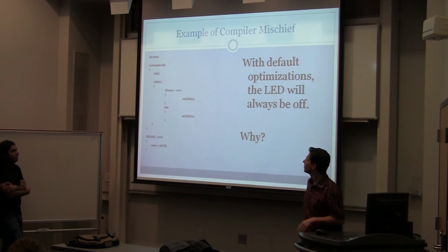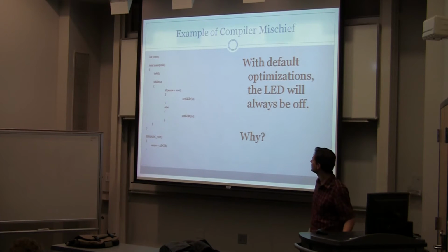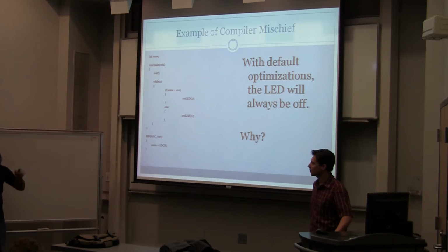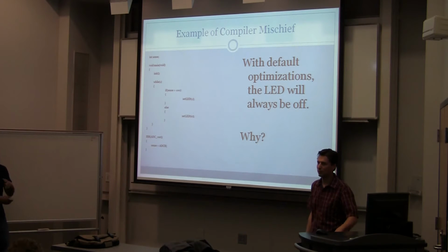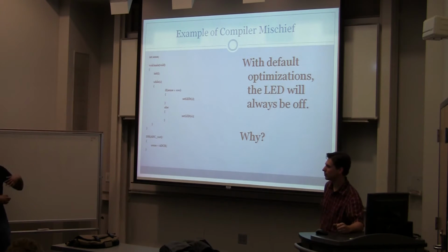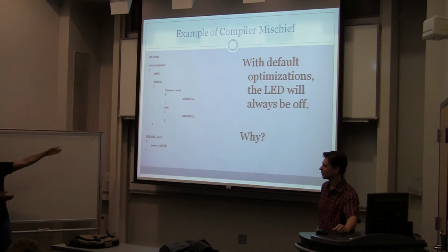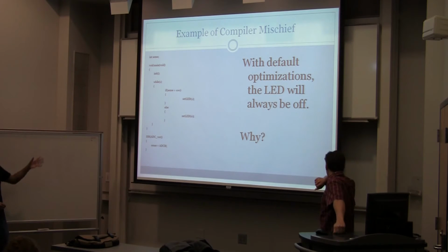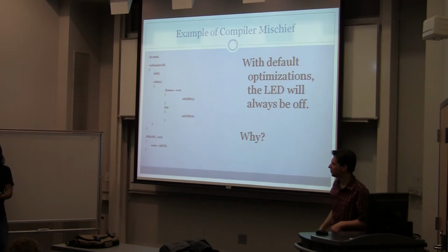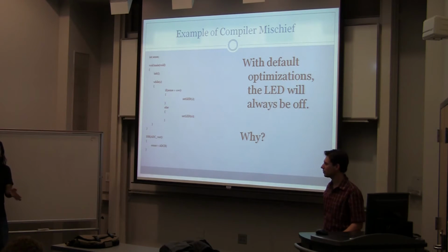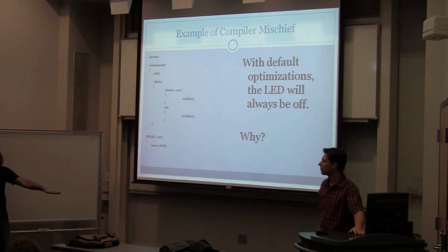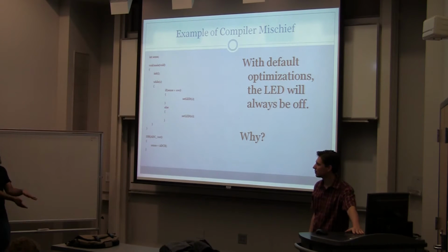Yeah. So essentially, when compilers are taking your code in, they do all sorts of optimization because there are a lot of inefficient things that you're doing that you don't even realize, and certain things can be compiled to very, very simple register instructions. So if you don't flag stuff like this, for example, volatile specifically says this is a piece of memory that could be changed from anywhere at any time. So don't make any optimizations that assume it hasn't changed just because I haven't touched it in one place.